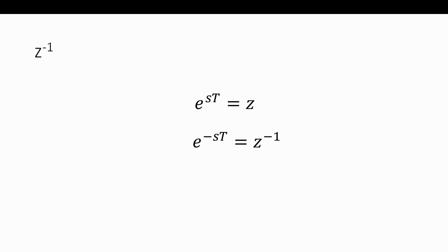So the Z to the minus 1 block that we see everywhere in DSP block diagrams represents the Z transform of a unit sample delay. So when you see it in a block, it just means you delayed one sample of the sampling clock. So it could be a flip-flop register that's taking the input, or a bunch of them taking the input data path. A clock goes, and now it goes to the output. That's one sample delay. That would be Z to the minus 1.